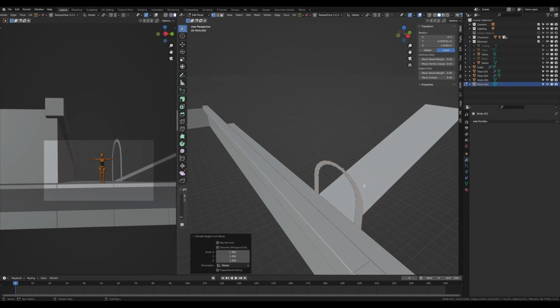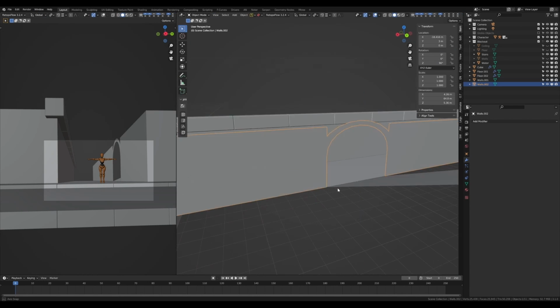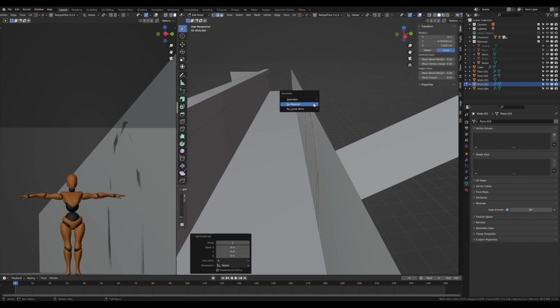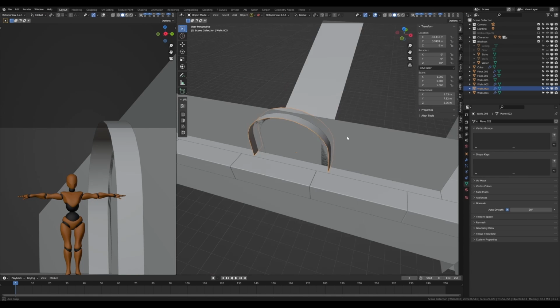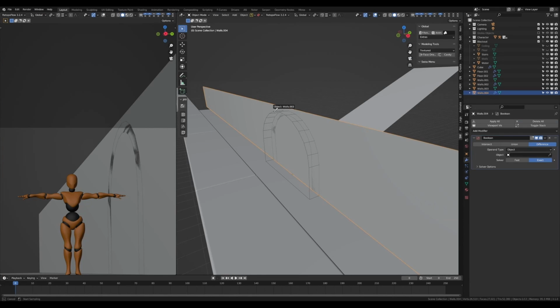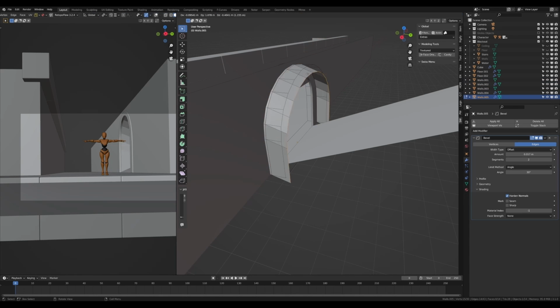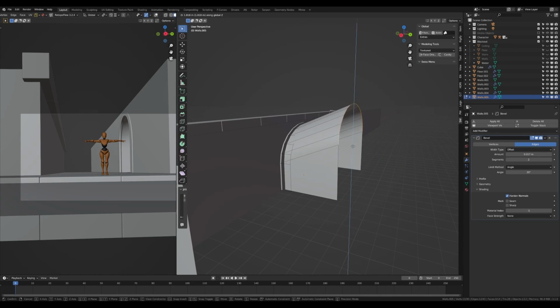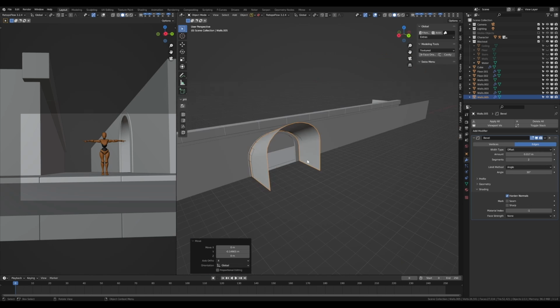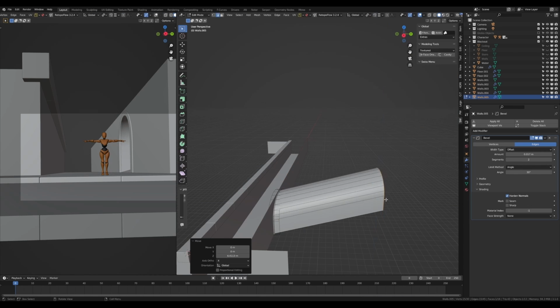To get the arch to interact with the wall properly, I'll give it some thickness, then trace it along its general area and use it as a boolean cutter to punch a hole, giving us our entrance archway. And by duplicating the general outline again, I used it to make the walls and ceilings of the stairways, and using some simple modeling, I moved the hallway up to match the stairs.